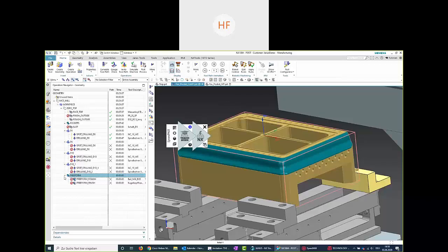And now let's reassign some similar faces, some extreme faces, for instance, the highest, the lowest, the most right face, and so on. Also the slot geometry in here. That one goes there, and the pocket shall be here. What else we've got? Yeah, we have some other in here. And I want those faces here to be 3D copy milled. For this, I'm taking this radio face and select it in here, that radio face selected there somewhere, and something like that. I don't have to reassign all of those faces, just some of them. By clicking on OK and OK,